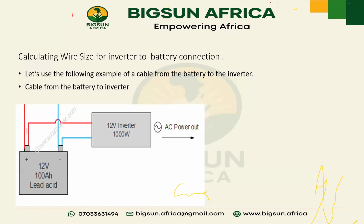Total output voltage is the voltage that you have calculated, whether in series or in parallel. So either way you are connecting, the total of your connection is what you are going to use. One-way distance is the distance from where you are taking, to the end point, either from your battery to your inverter or from your solar panel to your hybrid inverter or charge controller.